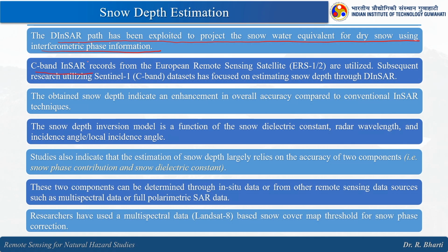C-band InSAR, we have Sentinel-1. Records from the European Remote Sensing satellite are utilized. Subsequently, research utilizing the Sentinel-1 dataset has focused on estimating snow depth through the DInSAR method, right. So, the obtained snow depth indicates an enhancement in overall accuracy compared to the conventional InSAR technique. So, today I will show you how our results are better than the earlier proposed model and how using this DInSAR helps us to identify the information.